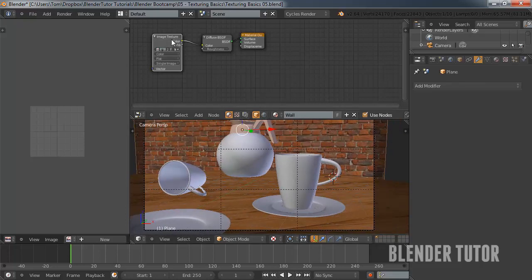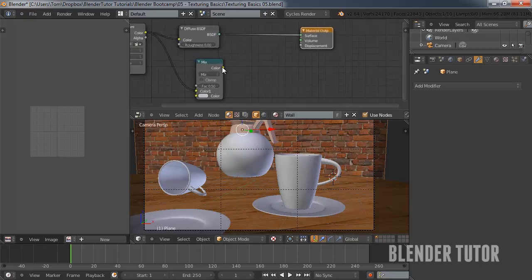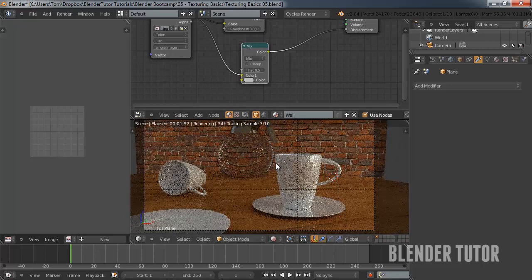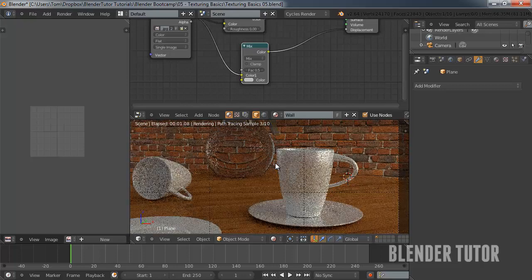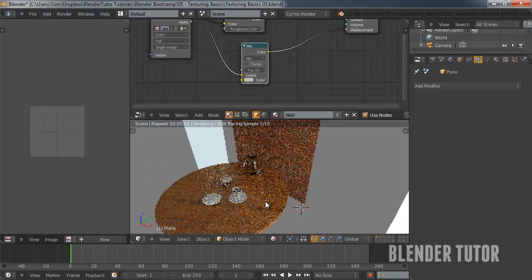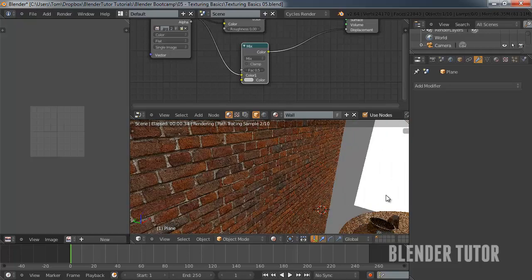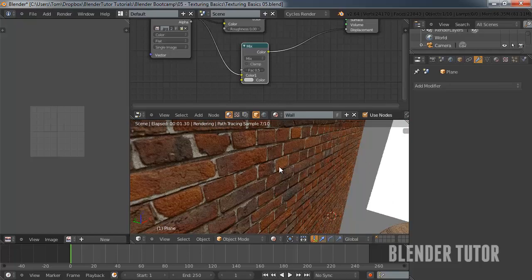And now for my brick, I'm going to do the same thing. I'm going to add a color mix node. Bring that over here. It'll be in the top one. And I'll put that in the displacement. I'll keep it at 0.5 for now actually. And let's look at that. Okay. Let me just see some light coming off this. I think it's getting a little bump, yeah.